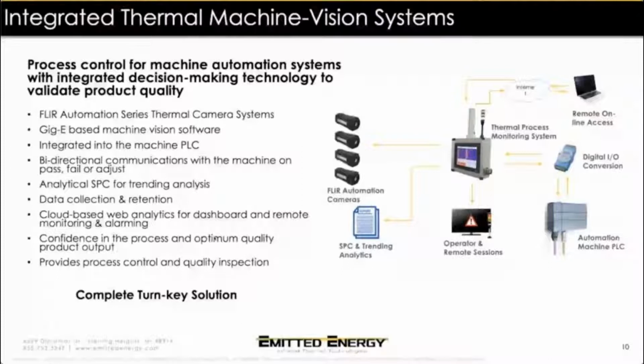We do data collection and retention. When we have an event that we are concerned with, we want to record and save that data. So we save the thermal images. We want full radiometric information to be able to go back and analyze what the problem is. We want that data in an Excel document, let's say. And again, we want to look at trend analysis. Why are we having issues on one particular part or one particular time in our manufacturing machine uptime? There's a lot of good information that we can drive to find root problems.